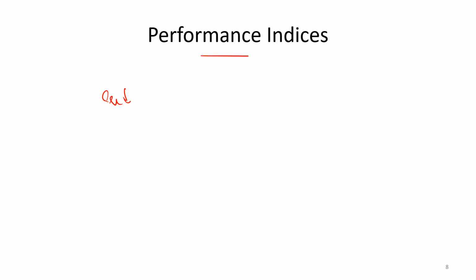How do you measure the performance? By setting the performance index. You say that this error should be 0.001 or 0.04. This is the criterion you set, and that is your performance index. Now you have to design a control system so that it produces an error of 0.004. That's why we say that the performance of the system is measured with performance indices.